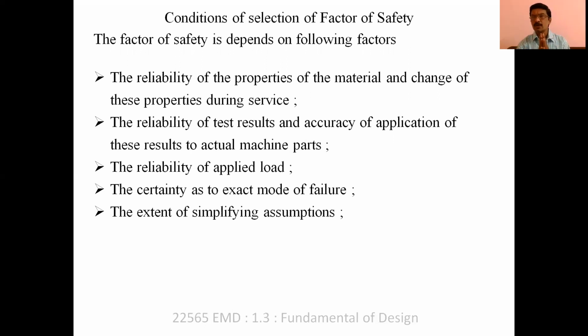Whatever assumptions we are going to consider, the factor of safety depends on that also. If you assume that there is a uniform material, then obviously if your assumption is correct, then you can take a lesser factor of safety. But if the assumption is not correct, then you should not take risk.